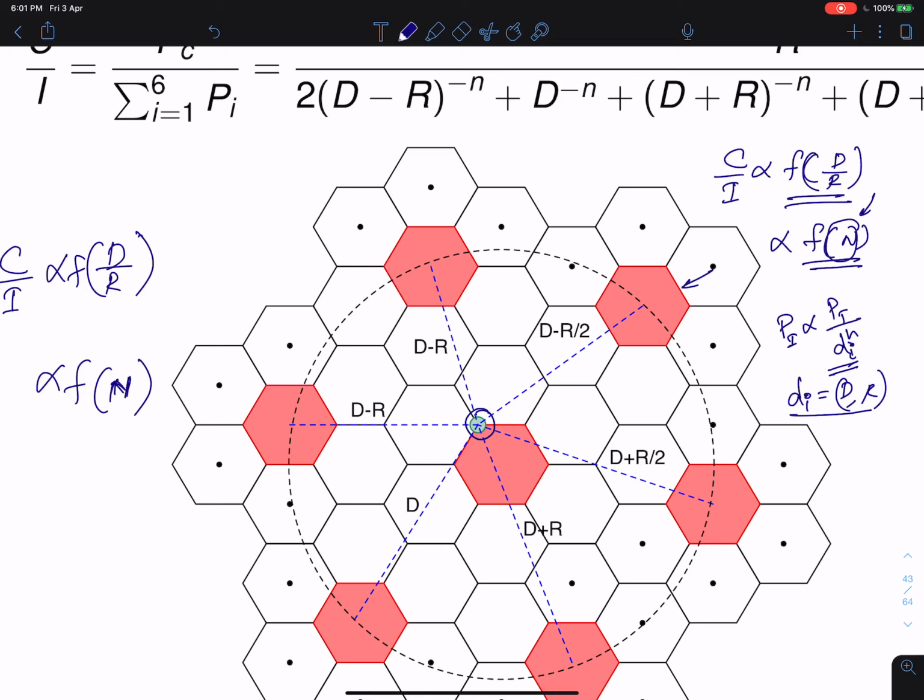To get an accurate estimate, you have to rely on field experiments and very good software, which can estimate interference if you feed in the geography information. The analysis that we are doing is a first cut analysis, so engineers can come up with a first order analysis to see whether this cluster size is okay or not.